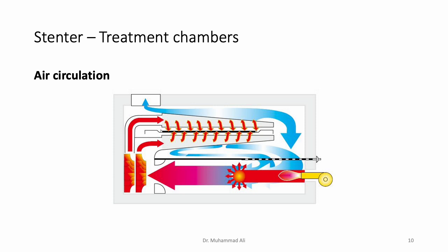So when we set the process conditions in a treatment chamber, we control the volume of exhaust gases, because that then determines the working efficiency of the Stenter, and that has a direct effect on the cost of our process as well. If we are taking in a large volume of fresh air in every cycle, then that volume of air has to be brought to the right temperature, which means more energy consumption. So it has to be the right balance between the amount of air that we are recirculating back and the amount of air that we are sending to the exhaust.